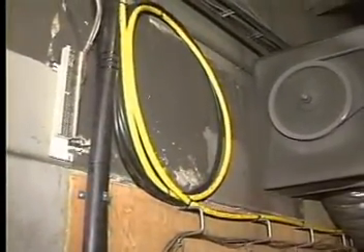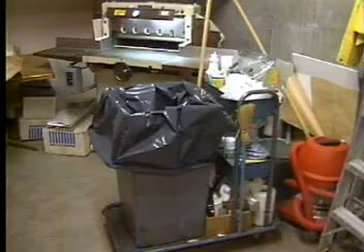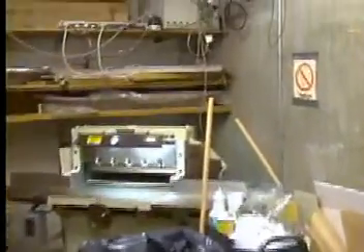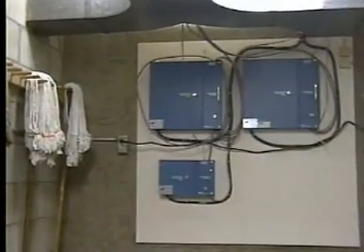It is in the user environment, however, that the most serious problems with contamination occur. Fiber optic systems are often located in dirty locations such as entrance facilities, janitor's closets, boiler rooms, and basements. In these places, it is very easy for contamination to work its way into precision optical connectors, degrading system performance. Thus, it is the user environment that must be given the most attention in connector cleaning.